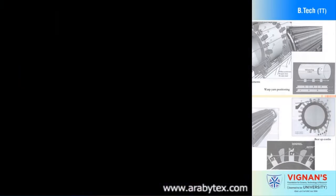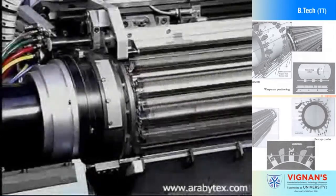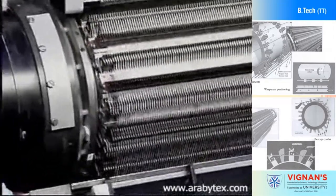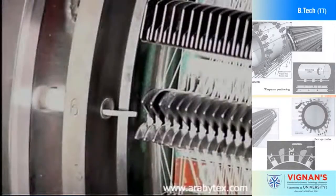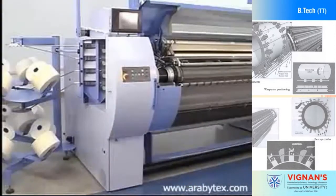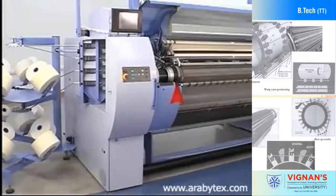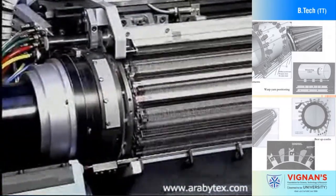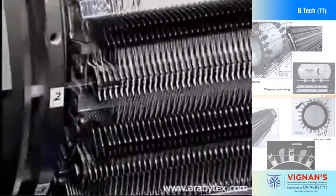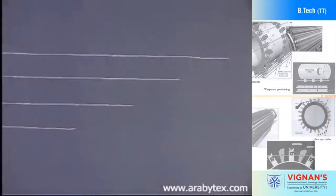The insertion unit distributes the weft ends into the weft channels of the rotor. The insertion unit takes weft from the static packages in the weft supply module and synchronizes the ends with the turning rotor. 4 ends are simultaneously inserted. Each end is staggered in position across the width of the rotor.